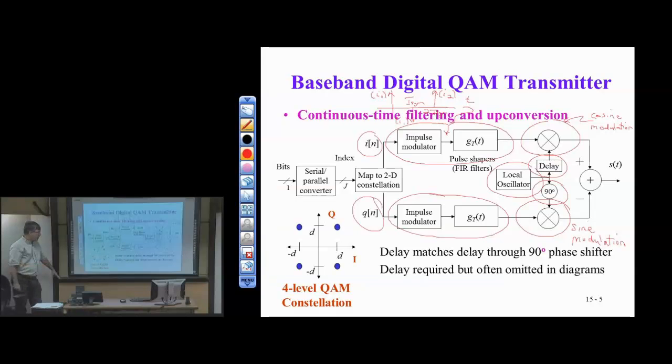And we'll talk about that in the next couple of slides. But that's in continuous time. In discrete time digital, why go through that? We know how to do it directly: a lookup table. In fact, we just do one lookup table, which is the cosine. And for the sine, how would you index into a cosine lookup table to get the sine?